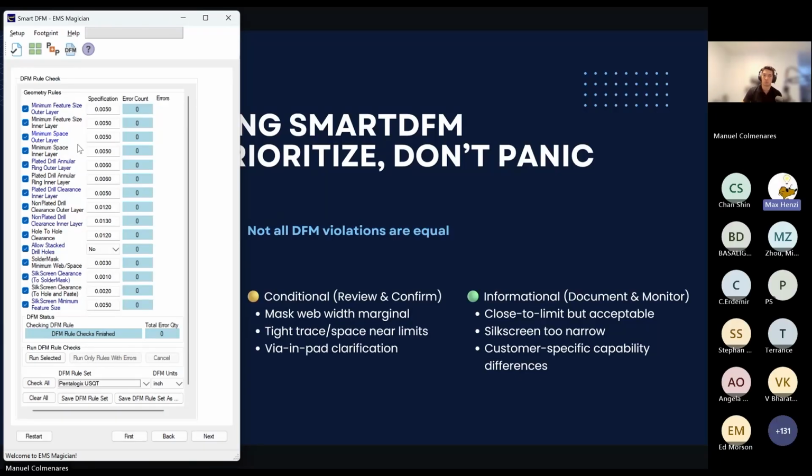I would say no. We look at a board as an entire board. So we look at it kind of top down from, say, top solder paste, top silk screen, then all the way down to bottom solder paste, bottom silk screen. It's sort of in that stack. Now, if you do have blind and buried vias, then you can define the connectivity in that screen that Manuel skipped in the beginning, which is sort of a drill layer stack up.